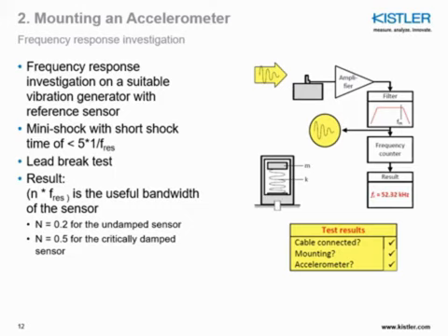So then you just need a scope with FFT or a data acquisition system with FFT and look at the frequency response of your system to see what is the first resonance peak. The resonance test is really useful in general. It can also tell you a lot about the sensor functionality, the quality of the sensor mounting, that's what we talked about, and whether the sensor is properly connected and the cable is working and so on.